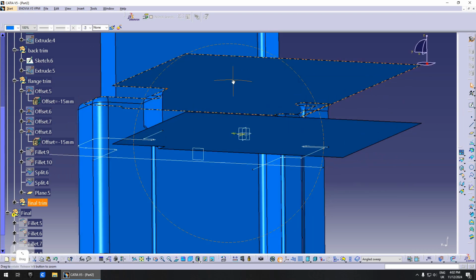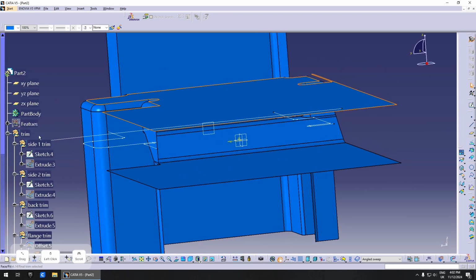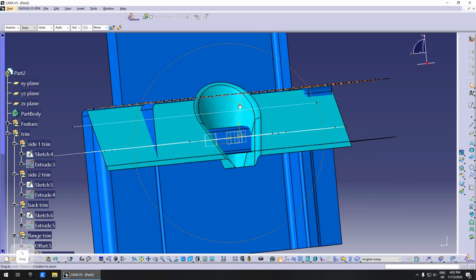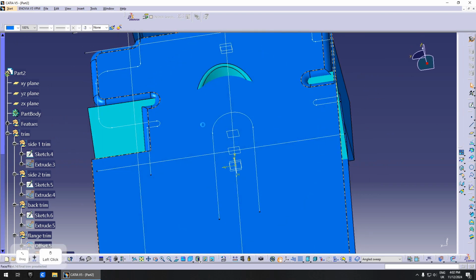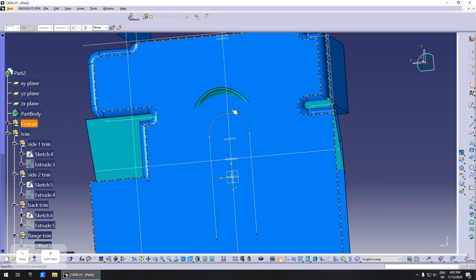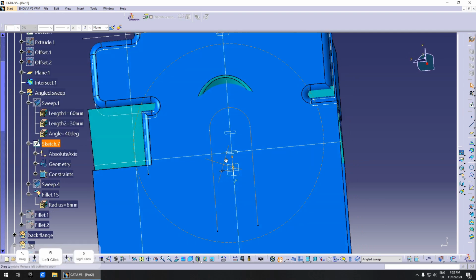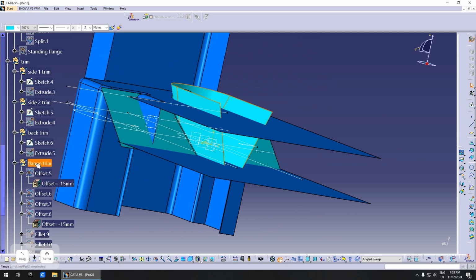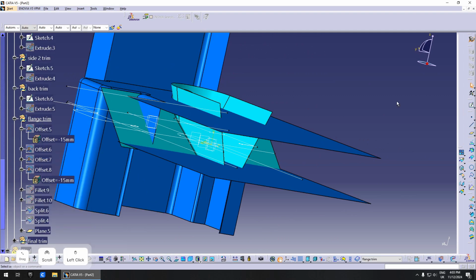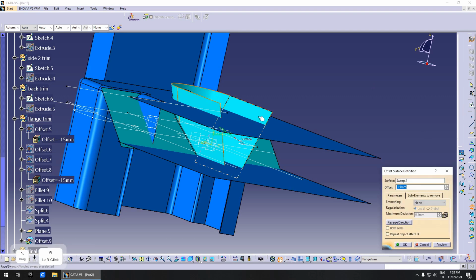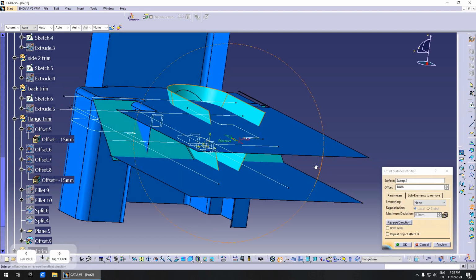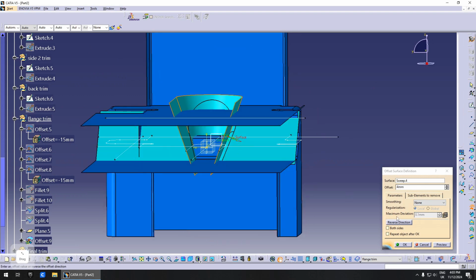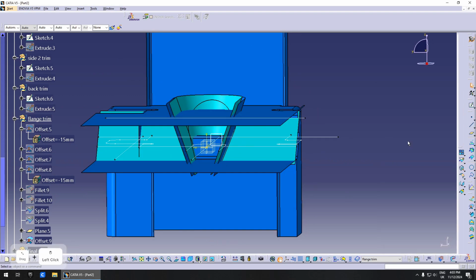In order to fix that, we need to cut away some of the trim surface around the problem area. So obviously it's gonna be this area here. So we already have the sketch, we have the sweep, we go to the trim. I think it's at flange trim. We can offset this by, let's see, 4 millimeters should be enough.